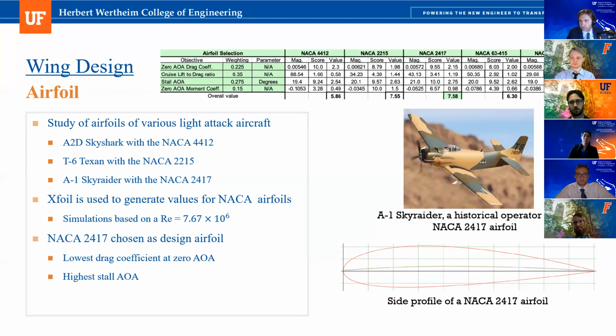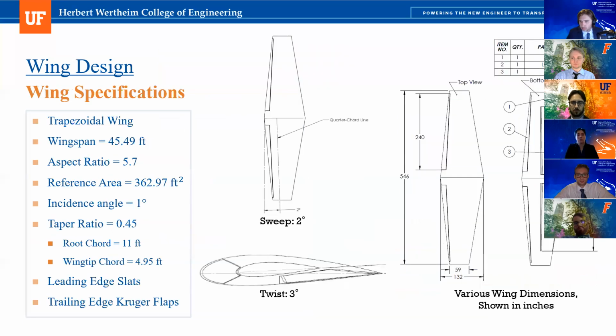And for the wing design, is there a page number? Next slide. Yes, this here. So the three you put as the critical flaps, I feel that it's all too big. You know what I mean? So the flaps, from what I can see from these CAD drawings, take up almost half of the whole area of the wing. I think it is too large.